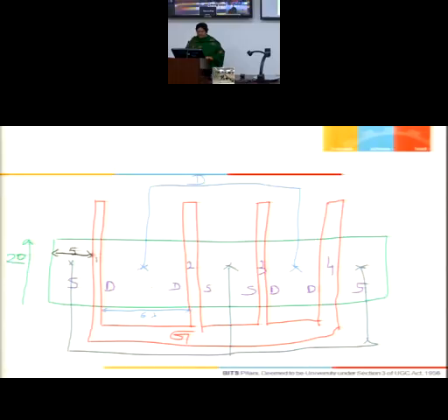What is the side wall capacitance of this area? 6 plus 6 only, because I have to neglect the face which is facing the channel. So it is only 12 lambda. So if I take two junctions, Akash from Goa campus, is it understood? There are two junctions, each one having a perimeter of 12 lambda. So total perimeter becomes 24 lambda, and total area becomes 240 lambda square. Yes, Manasa, is it clear?